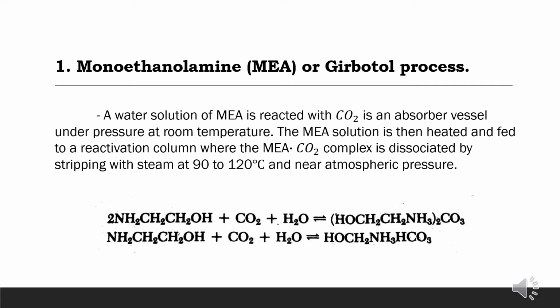Control of corrosion is achieved by using stainless steel at potential trouble spots, by limiting the concentration of MEA in aqueous solution, by limiting the CO2 in solution, by excluding oxygen from the system, and by removing the oxidation and degradation products using side steam distillation. Another system used a corrosion inhibitor, the Amine Guard, which has greatly decreased corrosion as an operating problem even with increased CO2 loading.